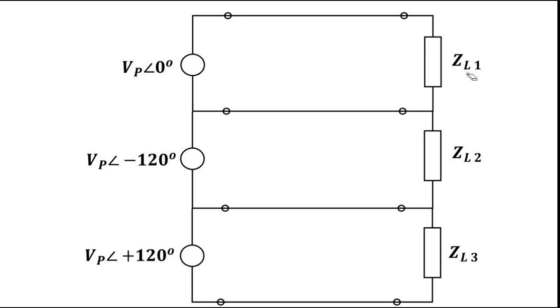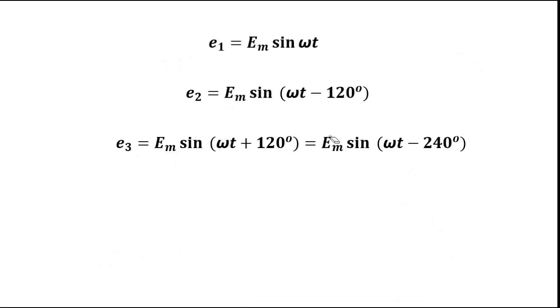Then we have three load conductors. We have three wires for each of the three voltages or windings, and a neutral wire. Depending upon the requirement, this neutral wire can either be present or absent. That gives us the three-phase four-wire system or the three-phase three-wire system. This is the representation of the different voltages or winding voltages starting from the alternator side to the load side.